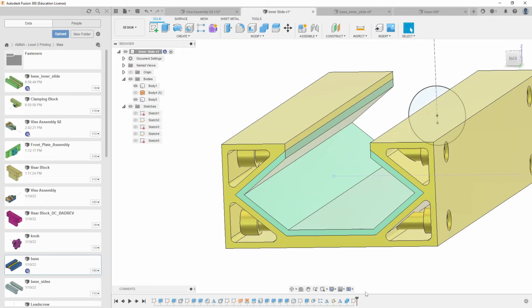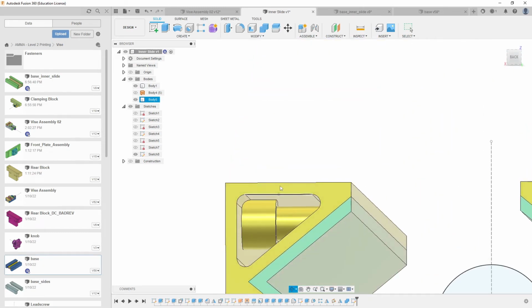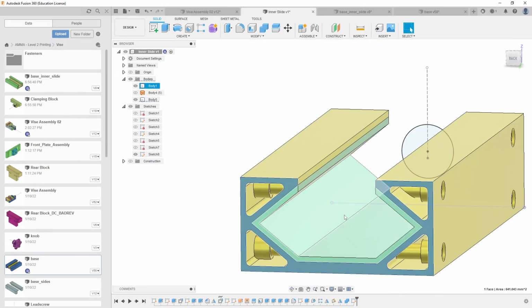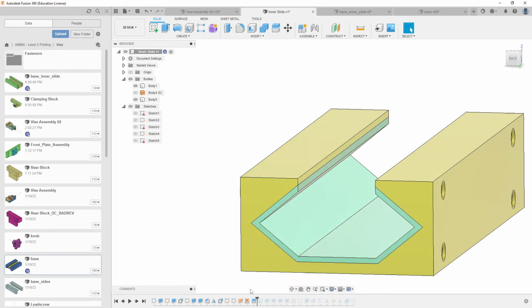If I did it at the very end, I'm going to thin this wall out, which I'm not horribly concerned about, because again, it's going to be like 0.2 millimeters. But if I want to be a little bit maybe better with it, what I could do, I believe, is I could come back here. Here's the shell where that happened, just after the body split. This might be where I want to do it, because that shell now will include that tolerance.